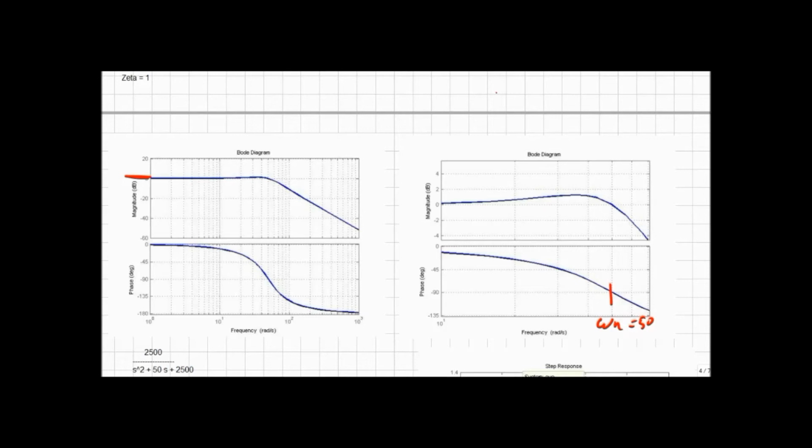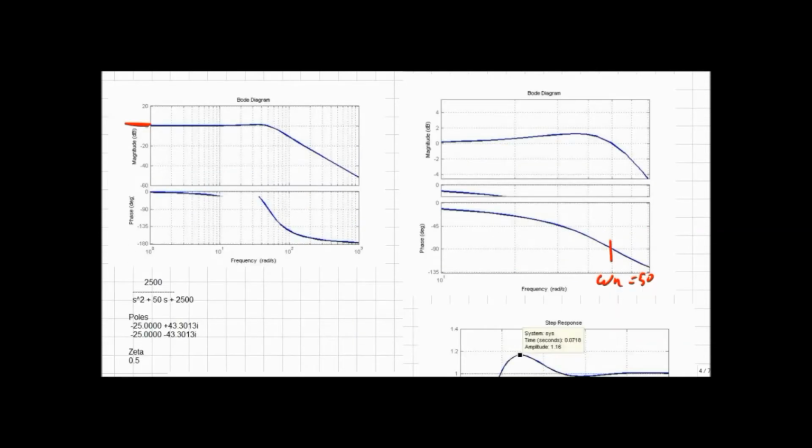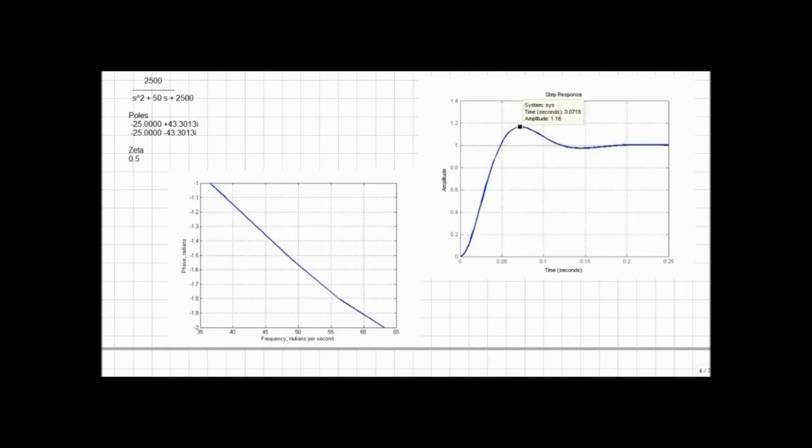And for the phase, I can use the slope method. But to use the slope method, I can't do that directly from the Bode plot, because I need a linear plot of frequency in radians per second, and phase in radians, not in degrees. The Bode plot tends to be in degrees, so I've got to make a whole new plot. I look for the phase to cross pi over 2, which is 1.57, and that happens at that 50 radians per second.